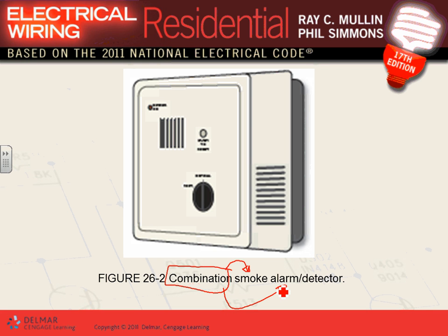The smoke detectors you put in a dwelling have three things in them, right? A mechanism to sense the smoke, that's the input. The output, when it senses the smoke, is able to announce the existence of the smoke in two ways. A loud noise coming out of it, right? And you also have visual, the visual indication of the alarm, so you announce it by visually announcing it, the horns and the strobe. See that one here? Horns and strobe. So we have a horn and a strobe and a detector all in one. That's how they do it in dwellings.